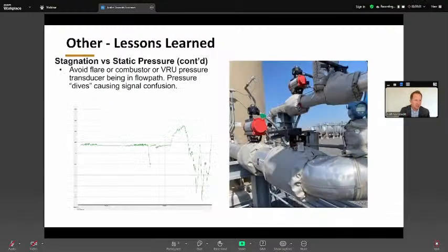And then lastly, you want to look at where you're actually measuring your pressure. In this situation, we've got a pressure gauge that is right here. I don't know if you can see my cursor, but there's a blue head in the right corner of the screen. That's your pressure gauge, and upstream, that red device is a control valve. So you're controlling the downstream of that valve, where you're not actually seeing what pressure is going on in your tanks. You're going to be seeing what's going on in your flare, and that's not going to be adequate control. So that's kind of the considerations when you're sizing your vent system itself.